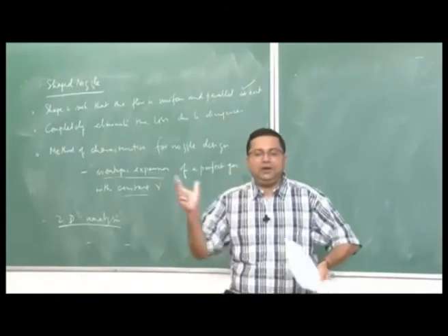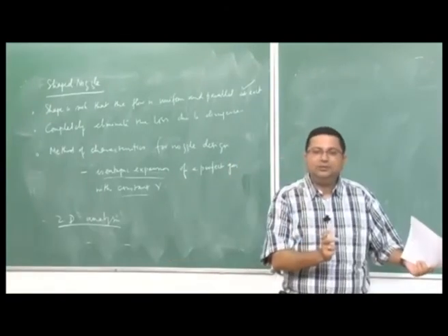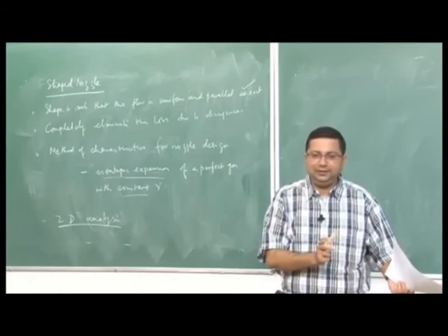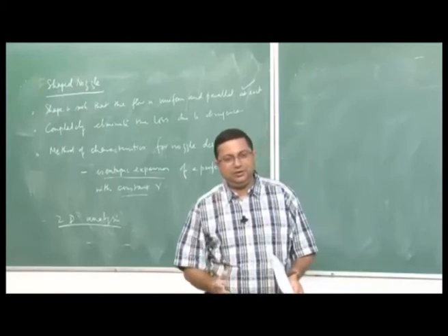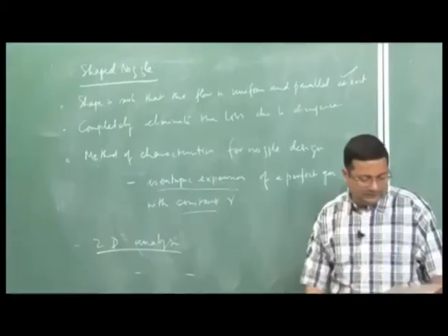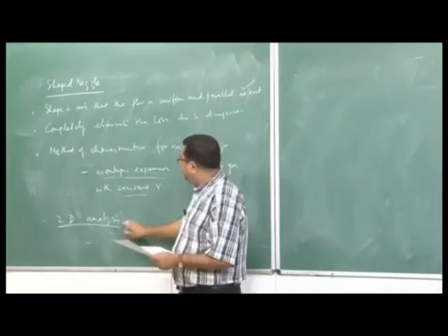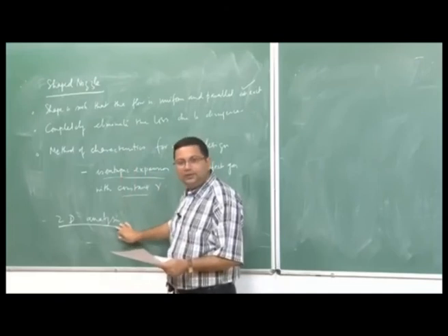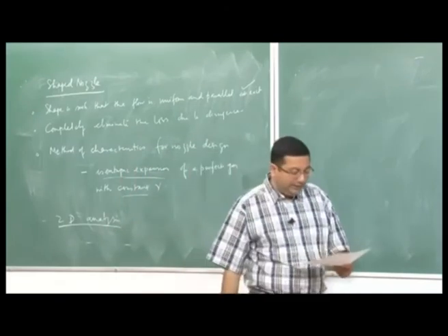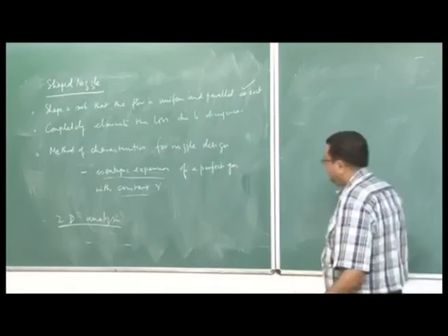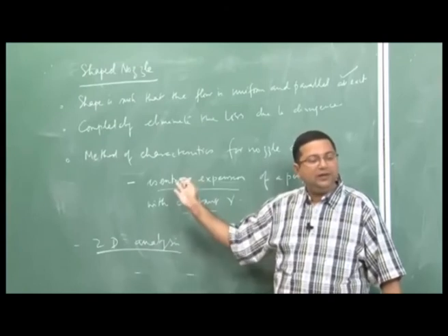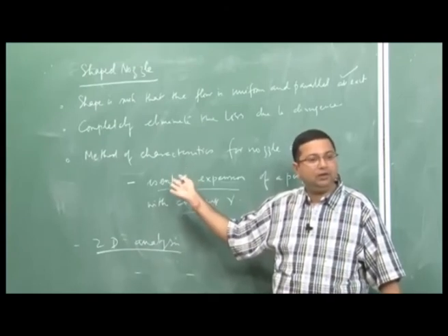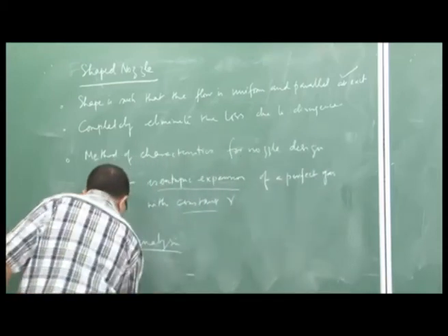Therefore, these divergence losses are somehow taken care of during the design itself, because we are considering the flow which is almost of real nature. Therefore, it is already considered in the design portion. And one of the things that method of characteristics does, since we are considering a 2D flow, is that it can provide significant curvatures to the streamlines. Since the streamlines will be curved, not the straight streamlines as we have seen in the case of the conical nozzle, here the streamlines will be curved.